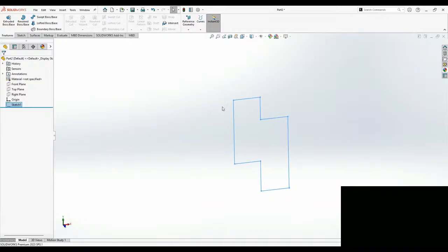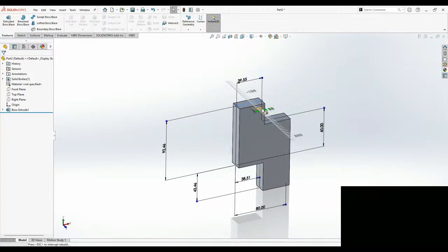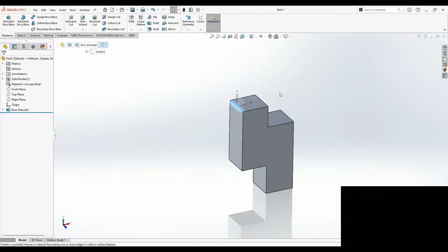This is how your sketch looks. You can directly activate the redirecting tool. Just drag it. If you press M, it will take both the sides, which is important with respect to symmetry. Done. So fill it. Shortcut I'm just using.